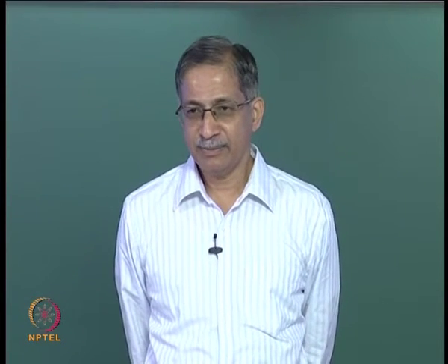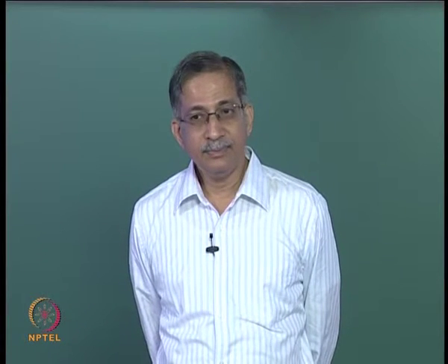This is one diagram. This is the diagram which we did in the previous problem. This is for RA, agreed? Why is the value negative in the sector BC? What does it mean to have a negative value? So it is sagging. So the beam segment in BC will be sagging.